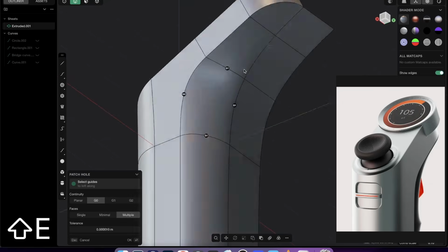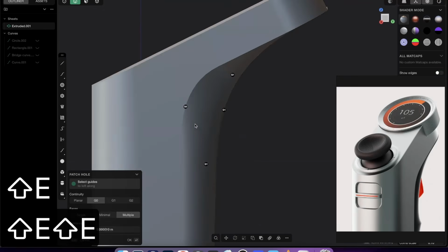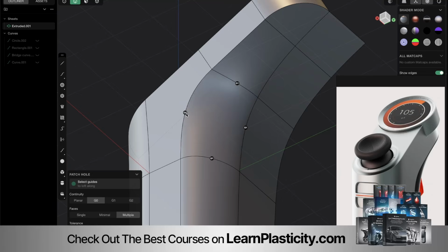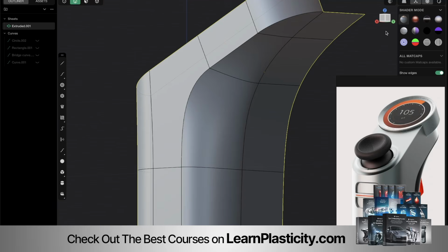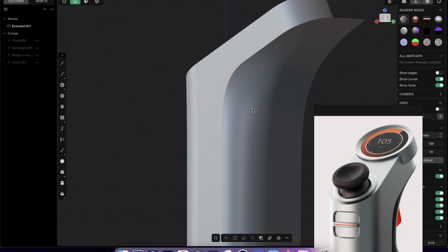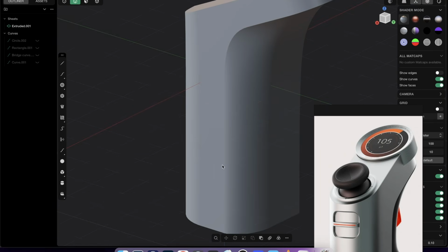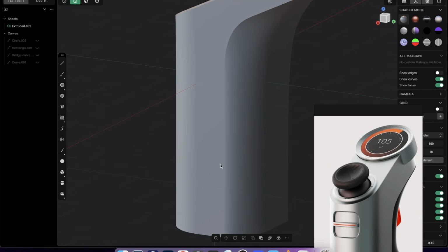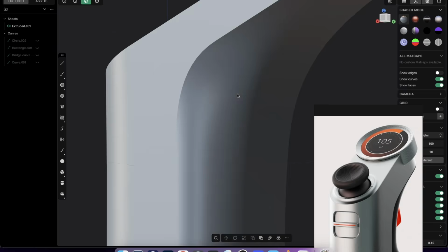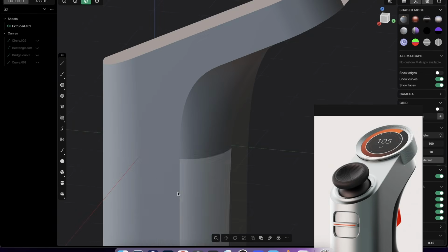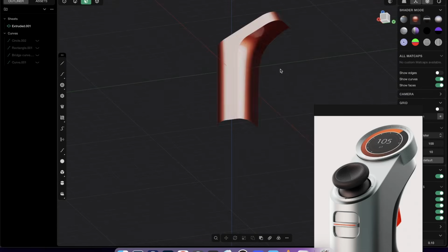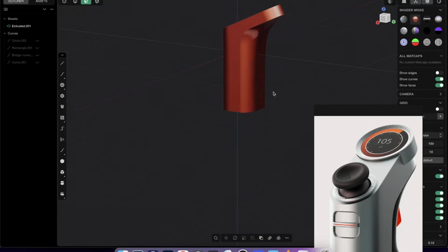And this looks fine. And very important, here you can't give G1 because then you get this, right? So it has to be G0. But the beauty is, if you unclick show edges here, you see, because we gave it G1 at the bottom, it's smooth. But here this face, you remember at this point we gave it G0, and now it's a smooth transition from smooth into a sharp edge, right? So this looks very, very nice and beautiful.